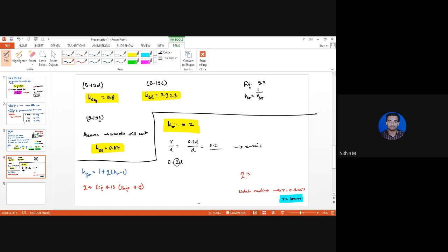And heat treatment. As the curve goes beyond 8, it becomes almost a line parallel to the x-axis, right? So if you consider normalized or tempered steel, beyond 9, however much extra, it will be a straight line. So here, for normalized and quenched and tempered steel, q is equal to 1. For normalized and annealed steel, it will be somewhere between 0.97 or 0.98. So let me approximate it as 0.98.